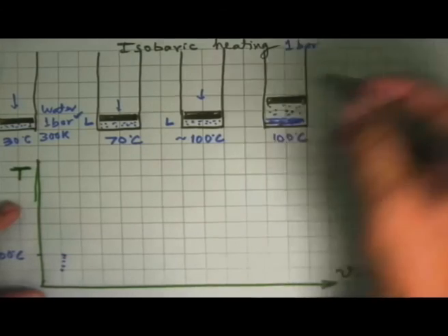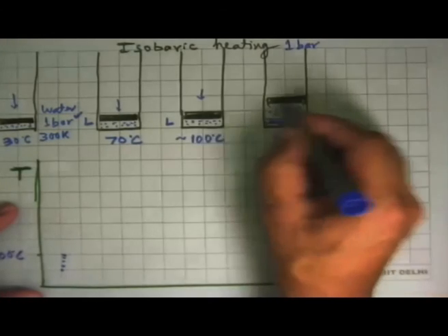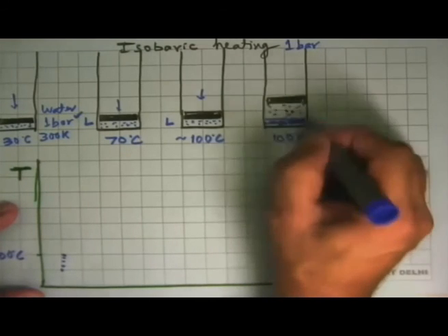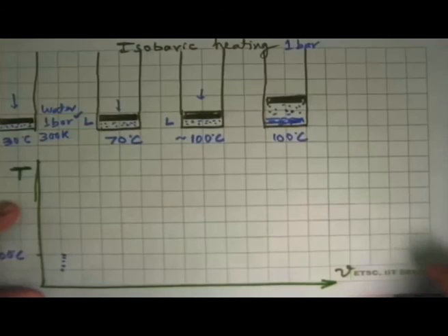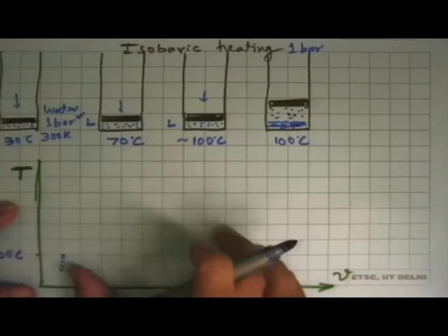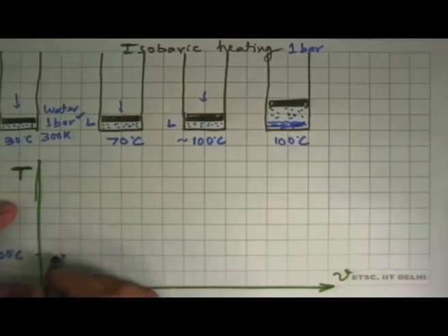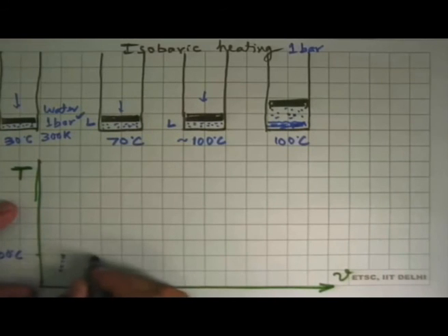So what we will do on this diagram is say, well, I'll just plot the total volume of this. So my mass is the same, volume has increased, so specific volume, meter cube per kg, that will increase and increase a lot without any change in temperature. So this state will now start moving along the 100 degrees Celsius line and say come over here.